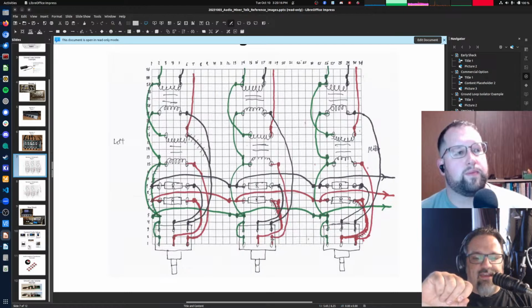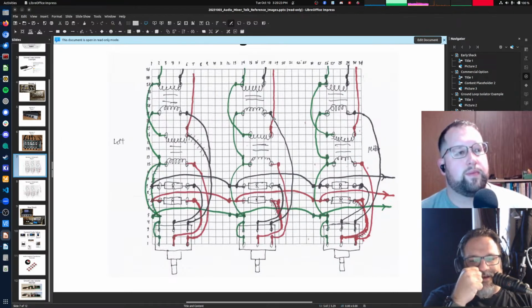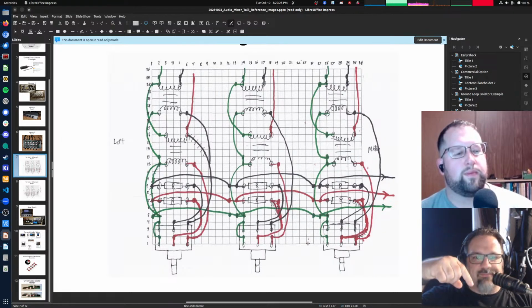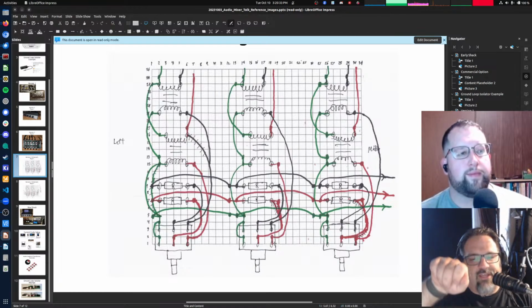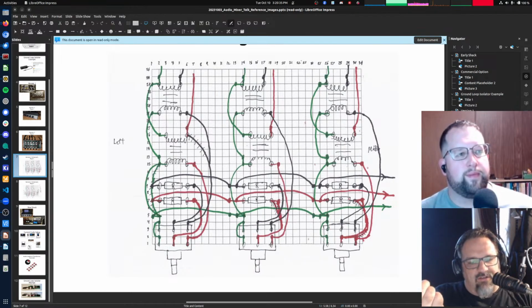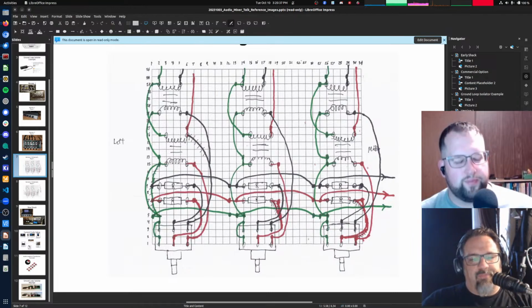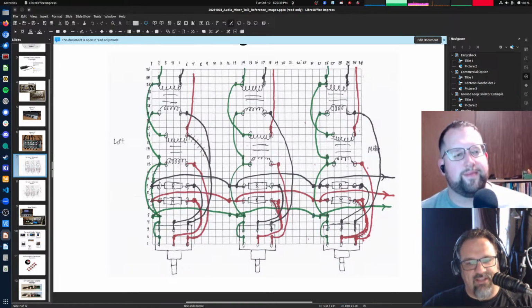And then the fully clockwise side of the potentiometer, which is the input to the potentiometer, is connected to the output of the isolation transformers. Right, so here's your isolation transformer, and it connects down to the fully clockwise side on your volume pot. And then same with the left audio there.